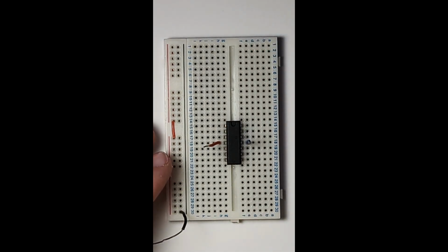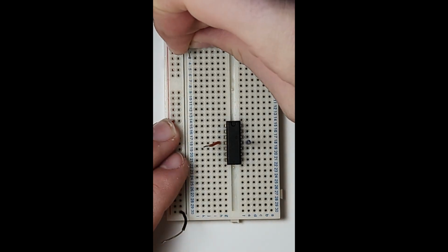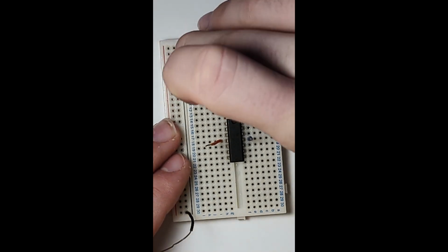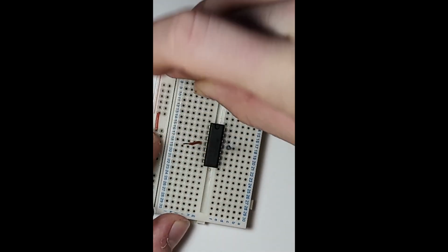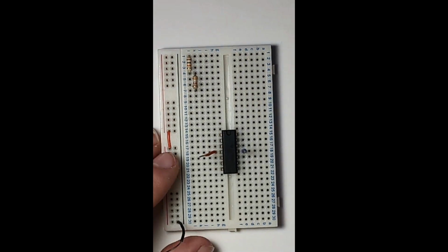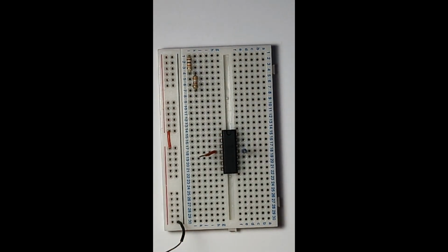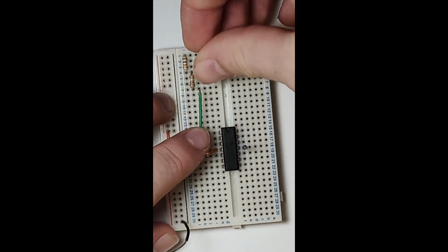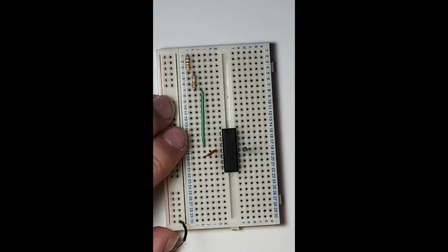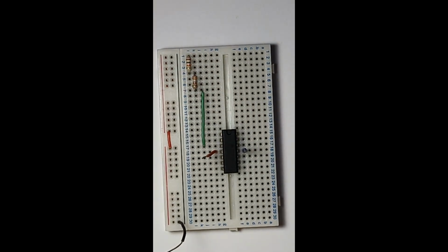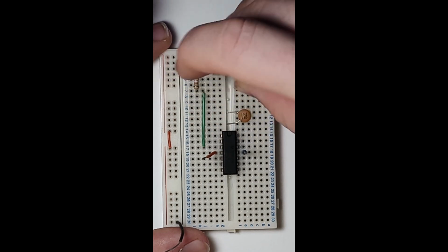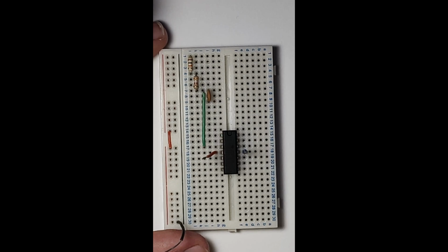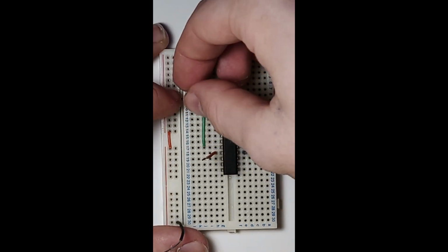So we'll start off with our 18 kilo ohm resistor right there and our 3.9 kilo ohm resistor just right beside it, just like that. So we want to connect the output of this second resistor to the positive input of the op amp. We also want this capacitor here, which is going to be C2, so it'll be grounded. So we'll also add in a grounding cable like that.